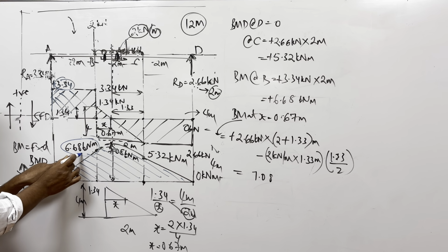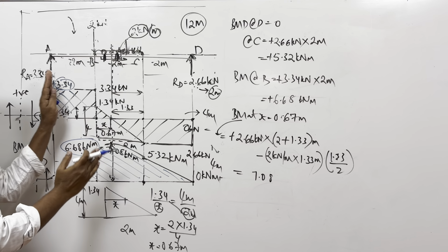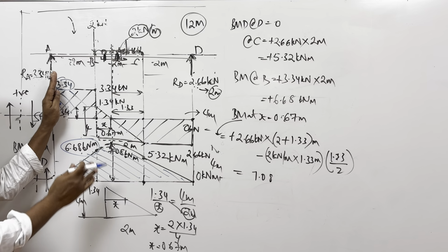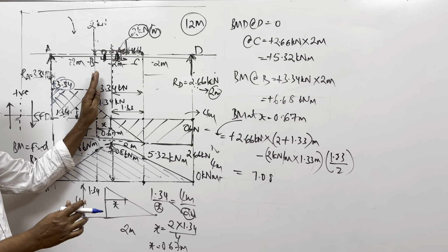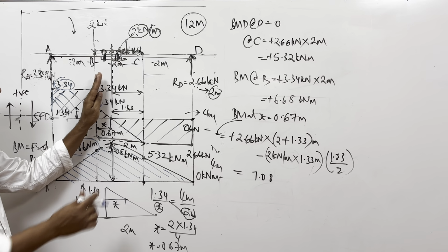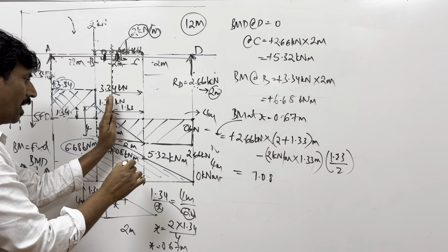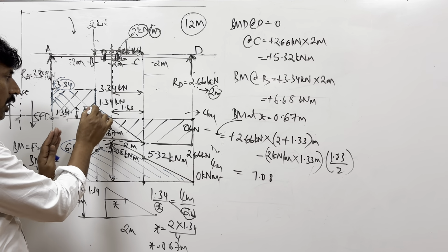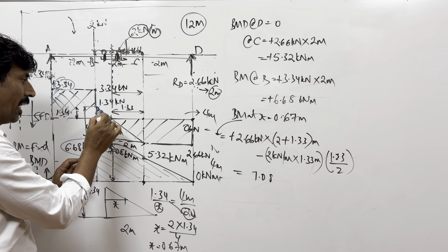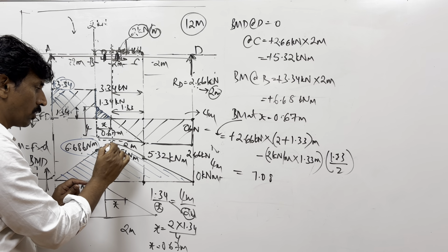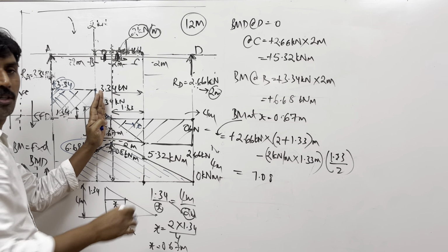Okay. So bending moment is the total summation of the shear forces. As you actually go from here to here, the shear force summation starts increasing and the bending moment starts becoming 6.68. And as you come here, you see that there is a sudden drop and this starts decreasing. Sorry, here it starts again increasing up to this point, okay? Because this area is getting added again. So it will have a small increment, and again from this point it starts going negative.